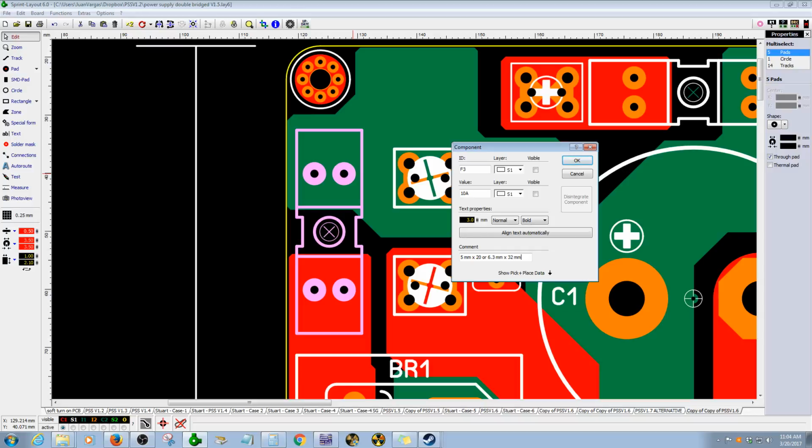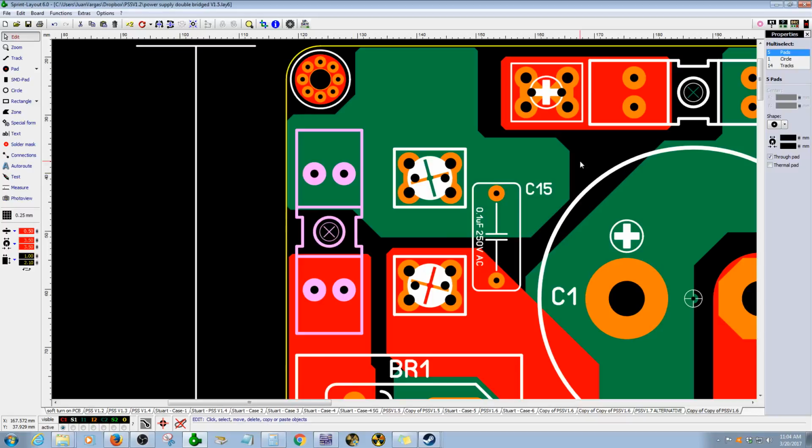That's why I selected this fuse, because here you can use 2 types of fuses, so if you don't have one size, you can use the other. So 5 by 20 millimeters, or 6.3 by 32 millimeters. So we have 2 choices of fuses right there.